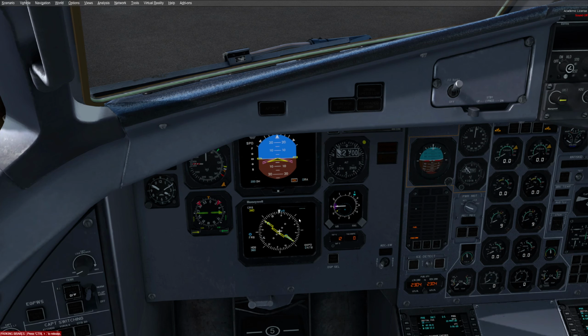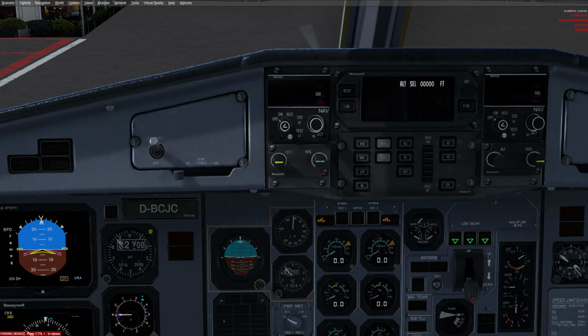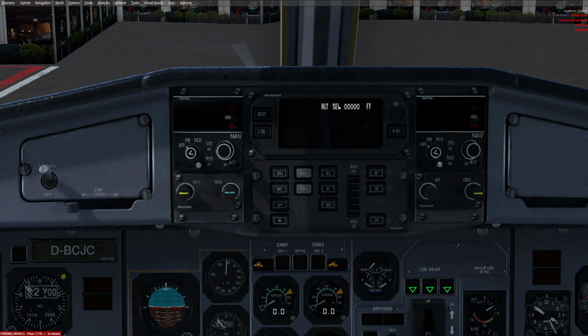The display select, that one will give you radar for weather, and also if you're in a dangerous condition with the terrain you can overlay that, and you'll get that advisory as well. The autopilot is right here in the middle. If it's in white letters in this area here, that's called the advisory display unit.